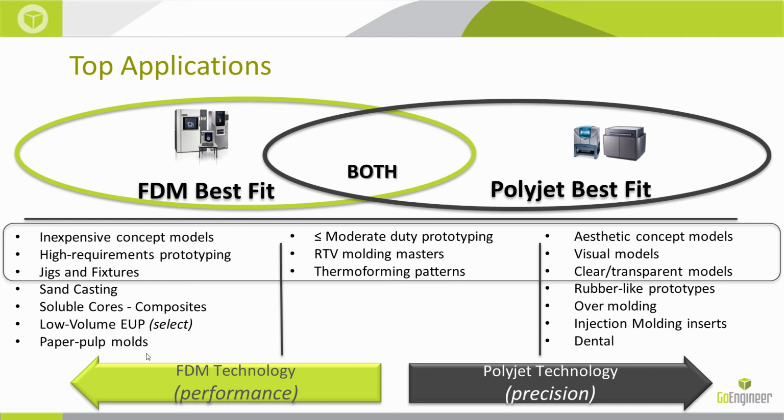The story behind that is they have the need for 100 or 200 parts a year. These were in the past injection molded parts, but the tooling for these has long disappeared. And Airbus hasn't really been able to justify the cost of creating new tooling. So they've actually turned to our FDM Fortis machines to print end use ULTEM parts.